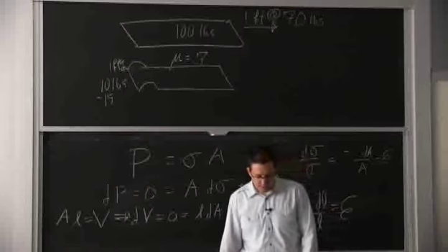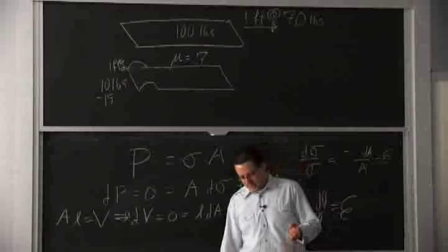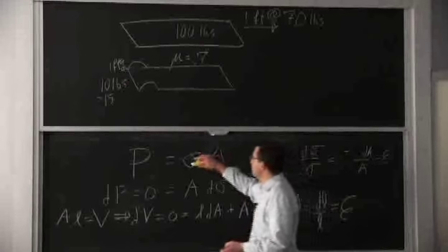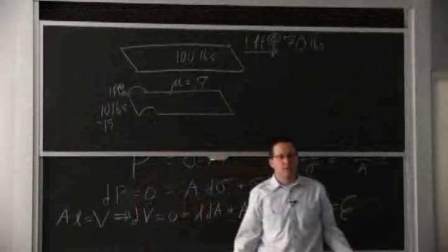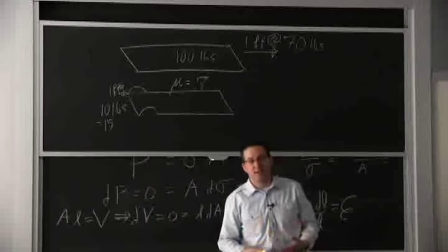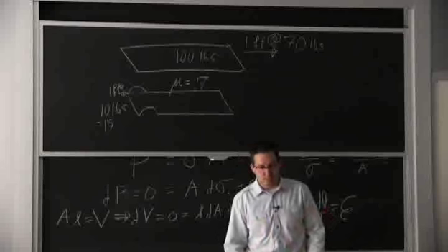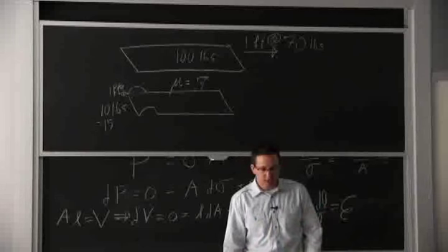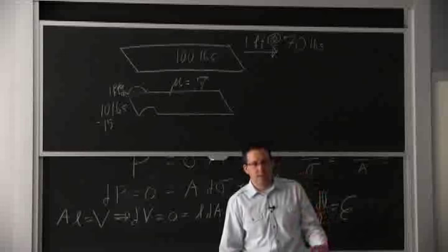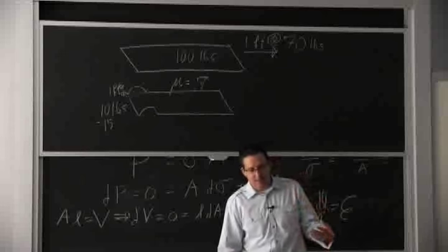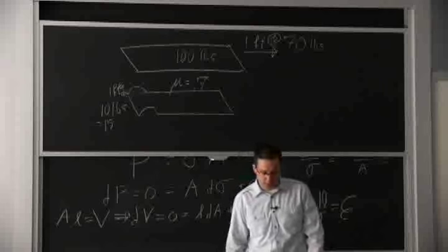Solids, obviously. We talked about rate effects, and the way I described it was it takes some energy to create a fold. We still have the fold right here. And the fold could happen slowly by itself, but you have to give it some time. Everything jumps around, and you don't know when that's going to happen. If you try to go really fast, then a lot of times you'll need more force. So the plasticity yield criteria will be higher for a higher deformation rate, generally.